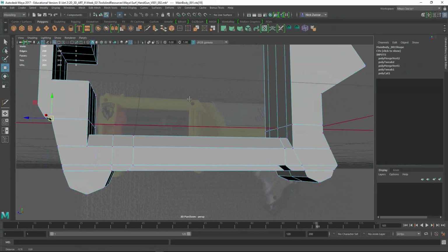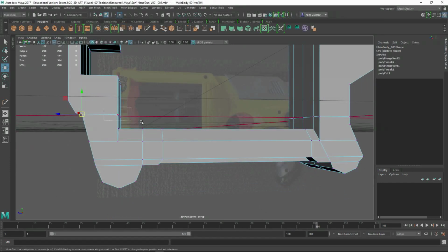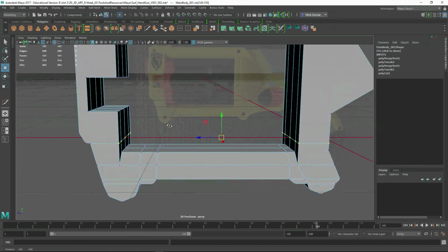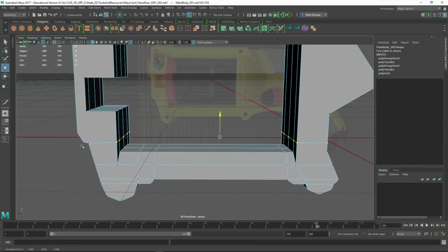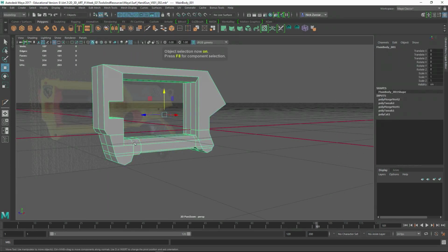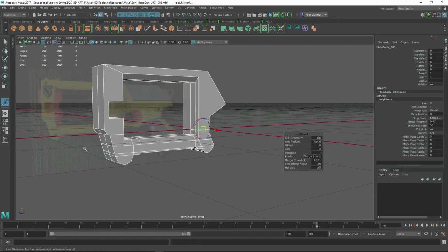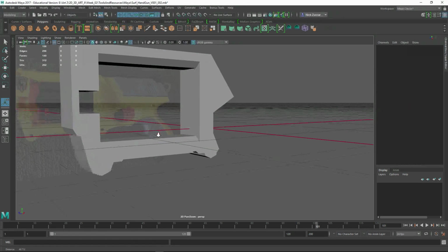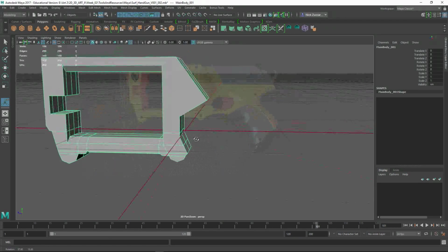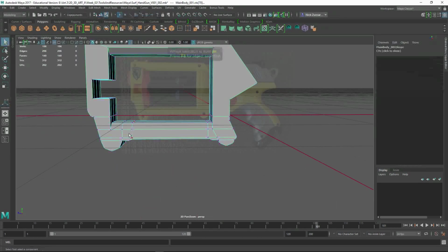And I should have everything else set up okay. Now I'm just going to take those verts and snap them. I'm going to hold down V and then snap to that level and make sure it's nice and even going straight across. And why I wanted to give myself a split like that, and delete history, Alt Shift D, I'll mirror it across again, delete history. I'm going to take the lattice tool, and I'm going to taper this geometry in. So I'm going to select all the verts up to here.